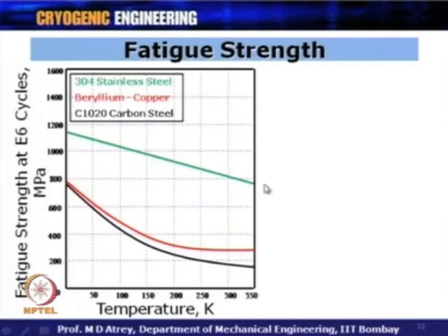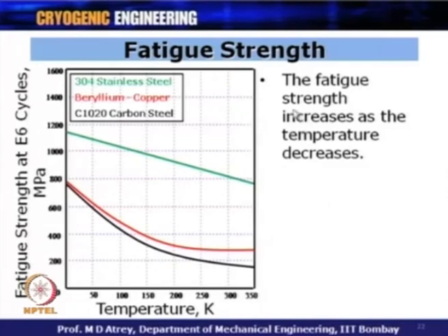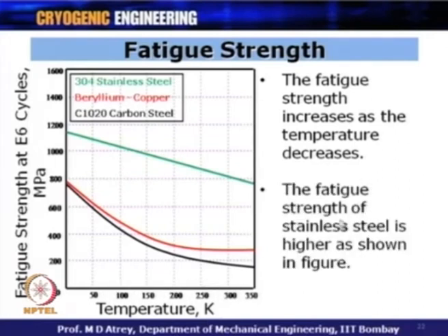So, again, the worst case for these materials is at room temperature. We can conclude again that the fatigue strength increases as the temperature decreases. As the temperature goes down toward the cryogenic region, the fatigue strength increases. The fatigue strength of stainless steel is higher, as shown over here. So, again, we can conclude that stainless steel is a preferred material if it is going to be subjected to